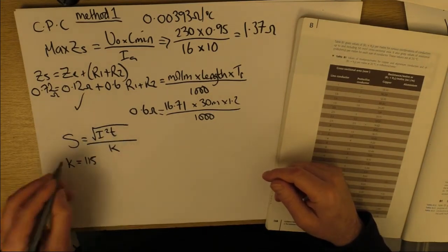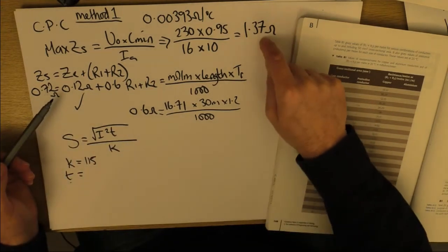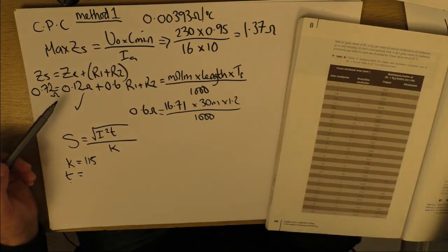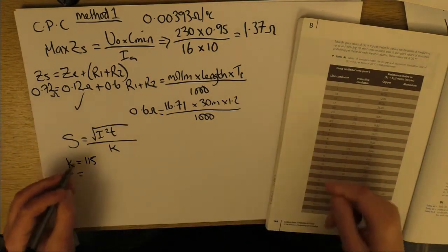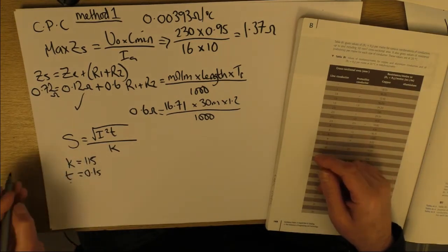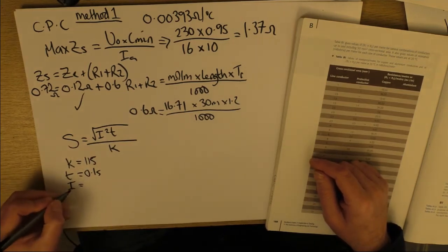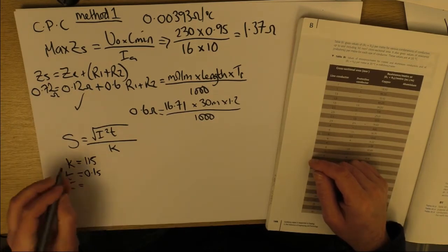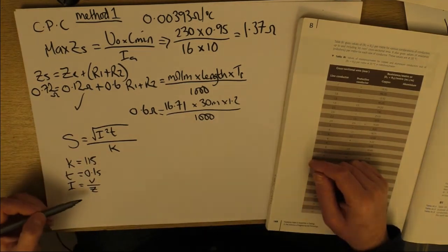Now T, because we know we're under the max ZS, we know that it's going to trip almost instantaneously. Appendix 3 in the regs, time current charts, I'll tell you that. But our T is 0.1. Now this is the fault current that's going to occur due to our ZS. Now it's just, you know, Ohm's law again.